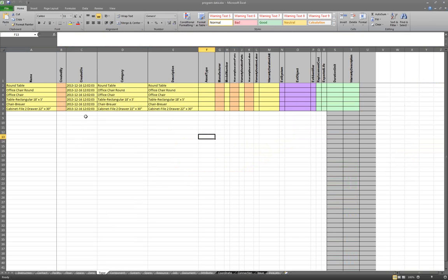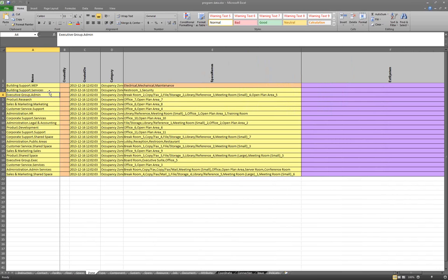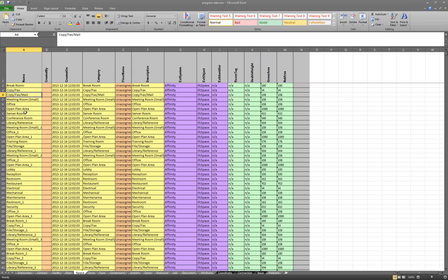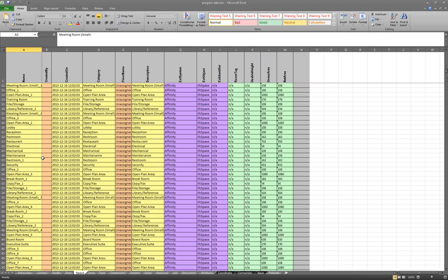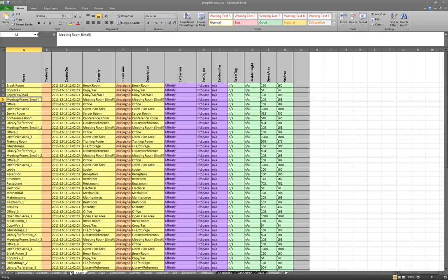All right. So this is an example of a COBie spreadsheet, the workbook. You can see that it's giving me all of my different components. I have all of my different zones or departments, all of the spaces within that project file. So it actually created this for me rather than me manually creating this on my own. The reason why people use COBie is because some government agencies have required that you do an output of COBie for their use.